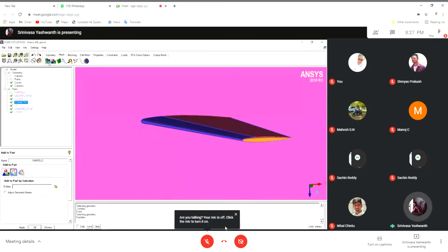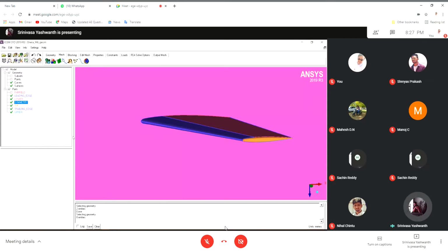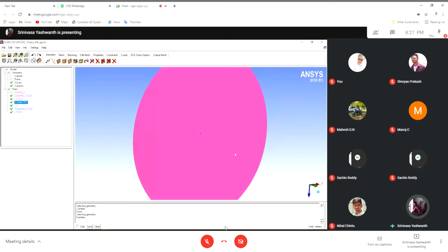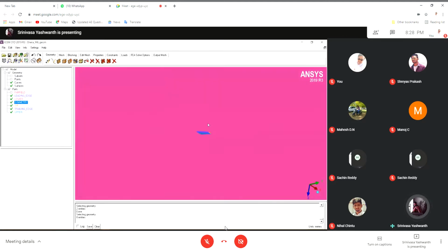Okay, so the first thing we do is we set the global mesh parameters. Oh, before this, sorry, there's one more step. You just have to understand this for now, I mean, take it for granted that the meshing softwares that are available in the market operate on single precision. That means the dimensions that are seen by the software are up to a certain number of digits. Say, for example, up to 16 decimals. That defines the precision of the geometry.